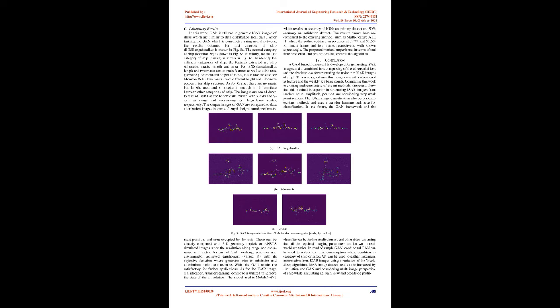B. Simulation of ISAR images. Initially, the ISAR images are simulated using electromagnetic solvers to train the GAN for generating the duplicates. The simulated and generated images are used for classification. The mathematical solver used to simulate the ISAR images is the ANSYS Electromagnetics SBR+ solver with RADAR pre and RADAR post as ACT extensions. The parameters used for simulation are shown in Table 2. The simulated ISAR images in range and cross-range axis, in logarithmic scale, are shown in Fig 7.